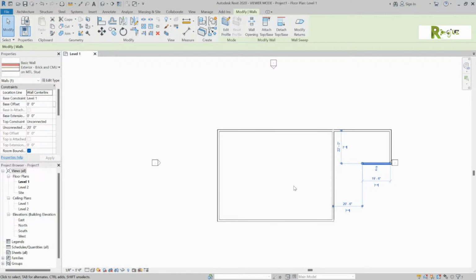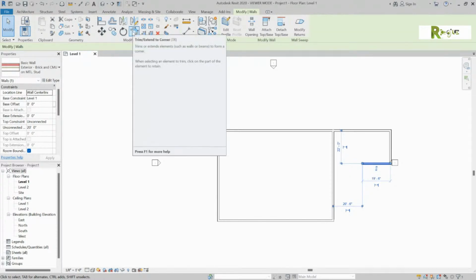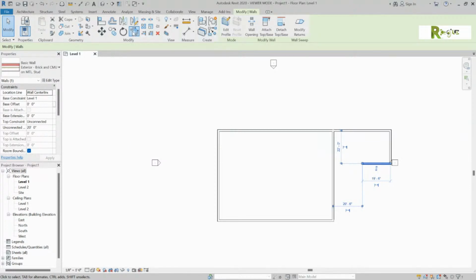So now the way a CAD user would always think, because in CAD we always had trim, a CAD user would think to trim those two walls so that they were open, so that you had the open floor plan. So up at the top of your screen, when you've got an object selected, notice the tabs. We don't have the wall as in our first one because we're not on the architecture tab. Because we've selected something, we're in the modify. So you would find the trim. If you come over to about the middle, you're going to see, there you go. That's the one. That's the one most CAD users would use, that they could trim and pick those two walls and it would trim them together. So pick on that and give that a try.